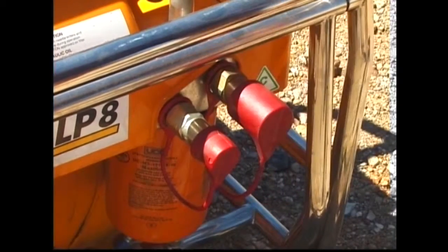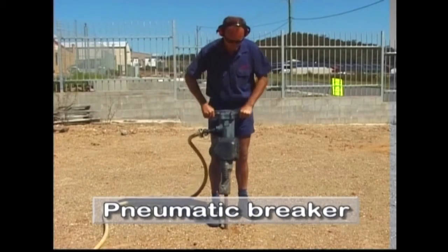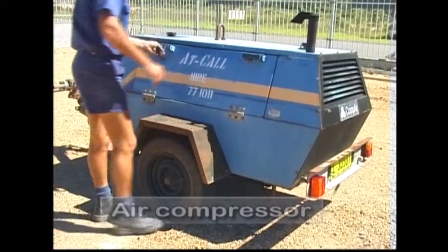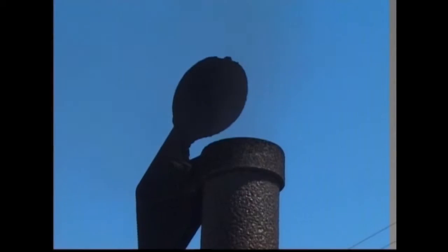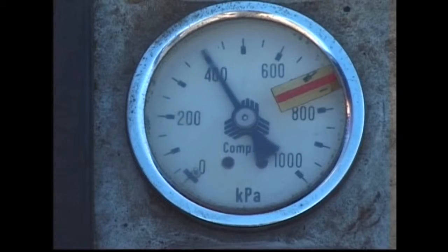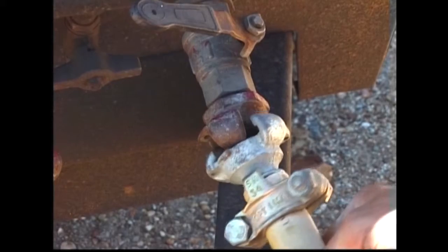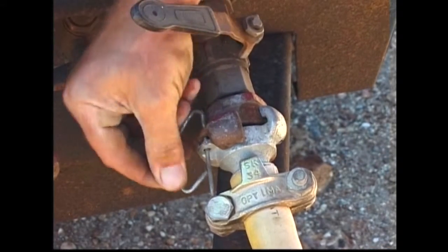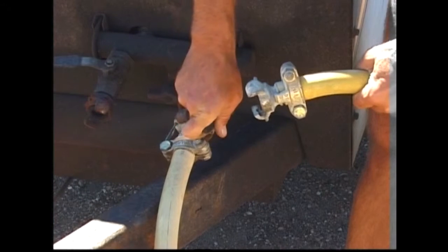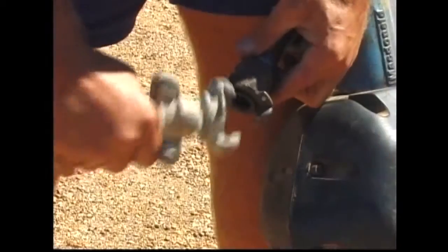Care must be taken to keep hose connections clean and free from grit. The traditional pneumatic breaker is driven by compressed air. A petrol or diesel-driven compressor delivers the power. The air hose must be securely coupled and pinned to the compressor. A short blast of air removes any grit from the hose before it is connected to the breaker.